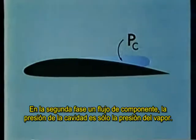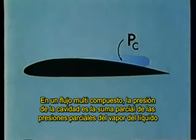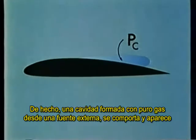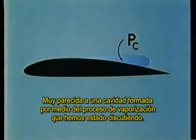In two-phase, one-component flow, the cavity pressure is just the vapor pressure. In a multi-component flow, the cavity pressure is the sum of the partial pressures of the vapor of the liquid and of any gases that may have been introduced into the cavity. In fact, a cavity developed entirely with gas from an outside source behaves and appears very much like a cavity formed by means of the vaporization process we have been discussing.